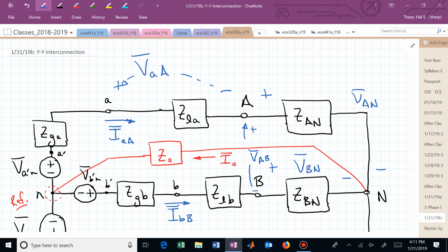So it's not the line voltage, which you could argue, yes it is, but it's the voltage dropped across the impedance in the transmission line. So the convention is when somebody says what's the line voltage, they mean between terminals from one transmission line to the other. Does that help?